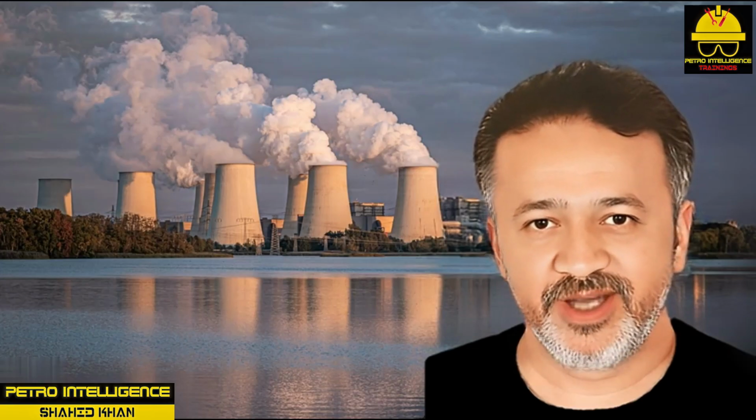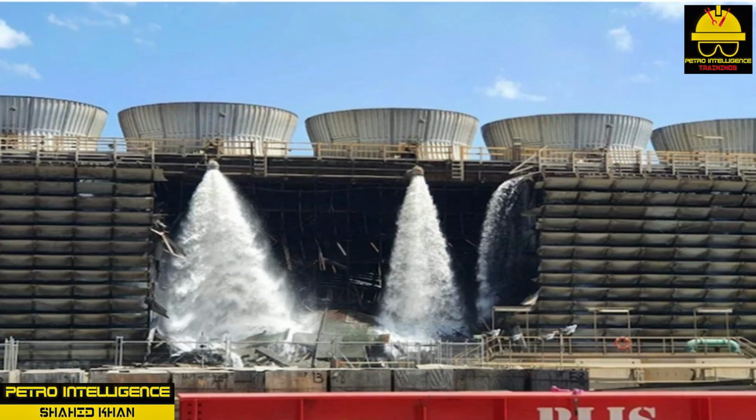Broken or collapsed fill. High winds, ice buildup, corrosion, microorganisms, and other variables can cause structural damage to the cooling tower. While a cooling tower is a simple design, it needs all of its parts to operate efficiently. Fill or splashboards can be replaced and put back in place. Bolts and brackets that have been corroded need to be repaired.